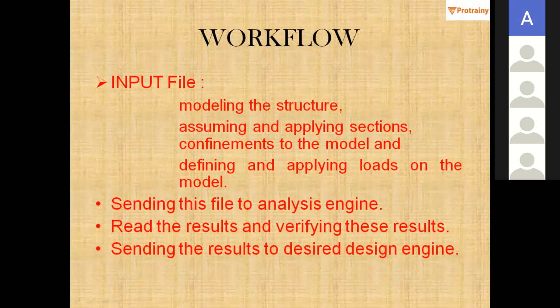What it entails is modeling the structure, assuming and applying sections, confinement to the model, and defining and applying loads on the model. The last part is going to be in the third week. First of all, you need to model the structure. Then you need to assume sections as well as the material you are going to use for this particular structure.